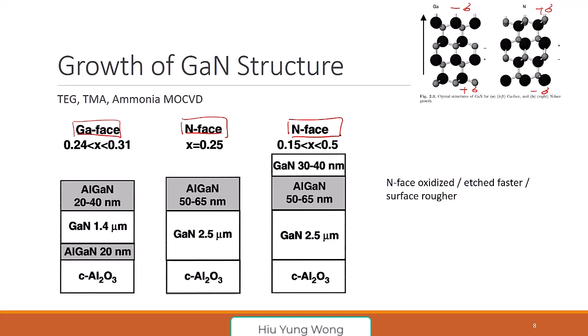And one thing also I need to tell you, earlier I said that for polarization, aluminum nitride is more than gallium nitride, just because aluminum is more electropositive than gallium, right? So the electron cloud will shift even more to the nitrogen. This is what I'm talking about, the electron cloud, right? Because aluminum is very positive, the electrons shift even more to the nitrogen. Is that okay? Just a very simple thought.